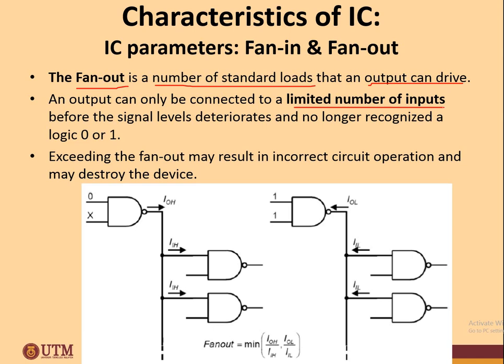If you put 6, then it's not working anymore, because you need to consider the loads. An output can only be connected to a limited number of inputs before the signal level deteriorates and is no longer recognized as a logic 0 or 1. So exceeding the fan out may result in incorrect circuit operation and may destroy the device.